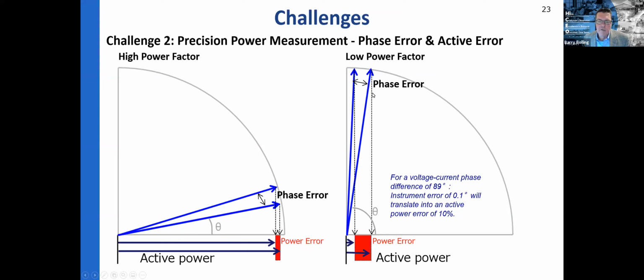Here's an example of measuring one of those power harmonics. So we have S apparent power, let's say at 100 kilohertz. And here we introduced just a couple of degrees, maybe several degrees of phase error there on the current side. And that showed up in S, which became S prime. That shadow that we cast down here turned out to be more than 50% error on this active power vector. So I hope that's a convincing slide for you.